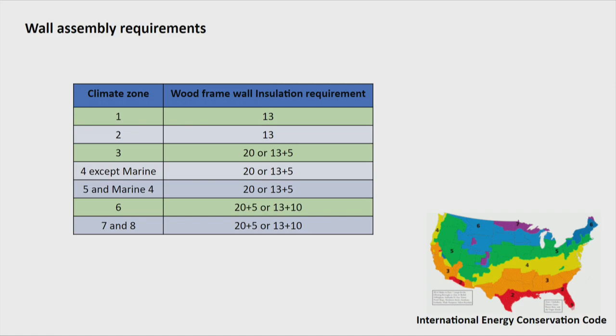And I think it makes sense to go through this step-by-step, of how windows become so bad in an envelope. So these are the current IECC standards. They're the climate zones. There really ends up being 3 different versions of this, which are highlighted in green here. Climate zone 1, which is the hot climates, the map is over here if you aren't familiar, is a 2x4 wall with R13 insulation.